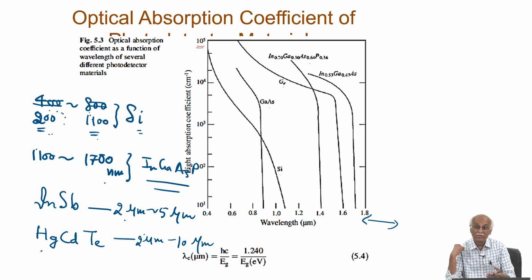That means the electrons generated will be very few, and even if they are generated, they will have to travel a long distance through the detector part. Even if you reduce that length, you may be able to cover the diffusion length, but the limitation is that absorption is quite large.